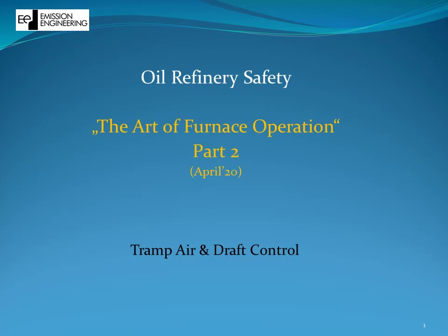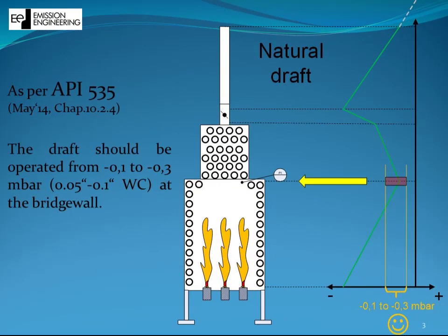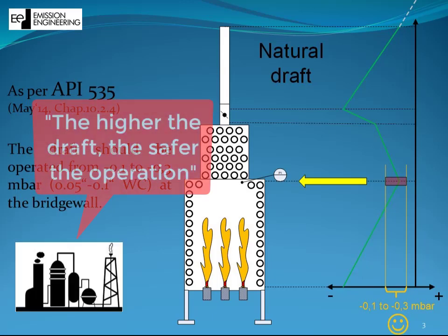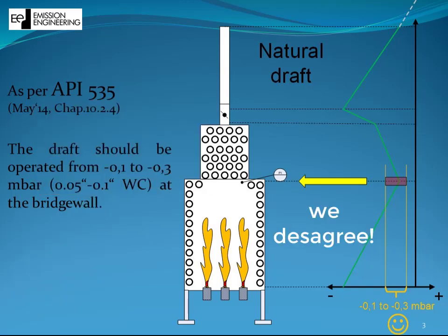Hello, today we'll talk about tramp air and draft control. A widely spread misunderstanding and wrong habit in many fired heaters in oil refineries is to operate with higher draft than necessary. A lot of people believe that the higher the draft, the safer the operation. But we will give you some contradictions today because we are not sharing this point of view.